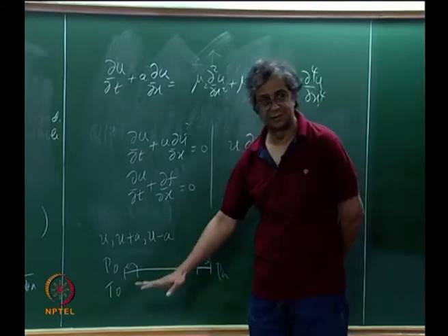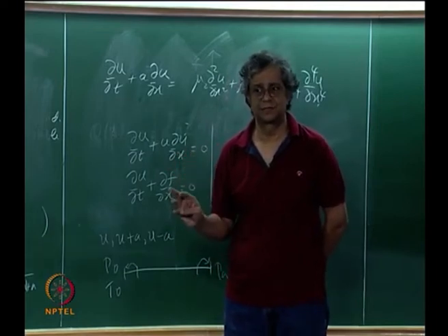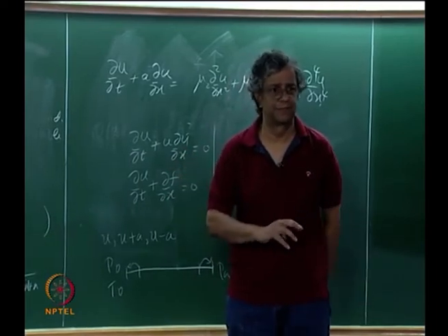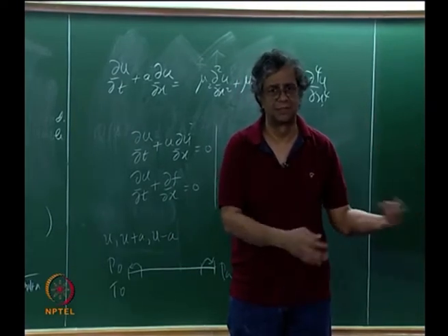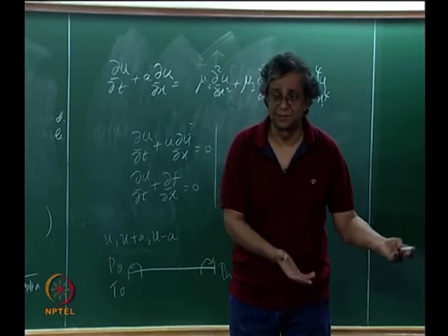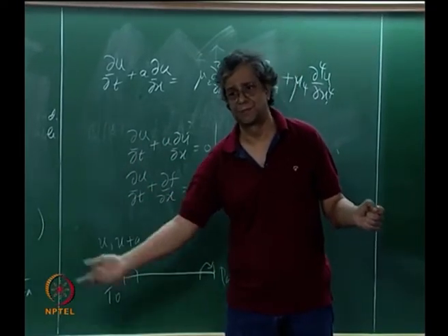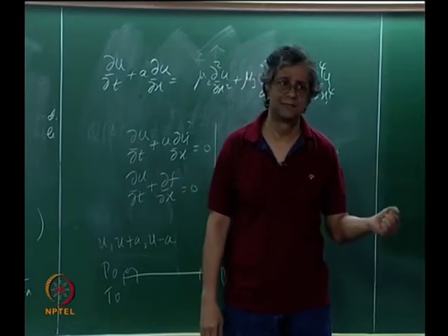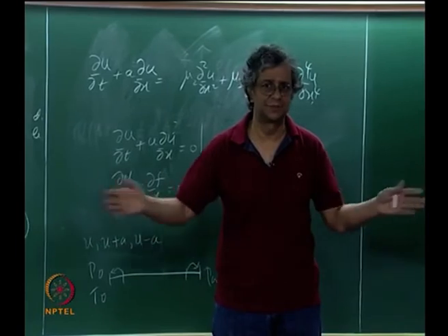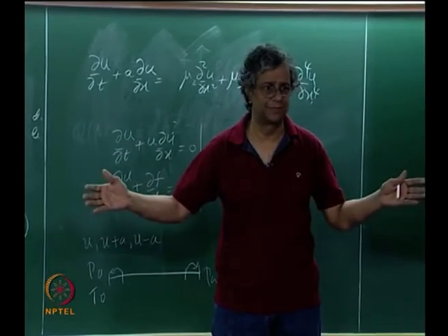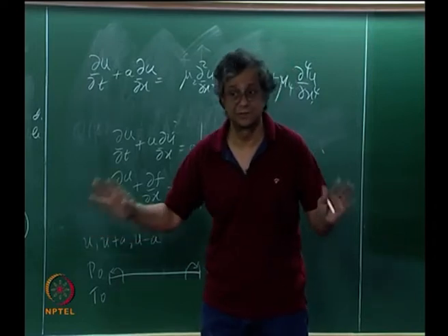The emphasis here is there are boundary conditions that you recollect, there are boundary conditions that are required by the physics of the problem. Your pressure vessel, the air in it has a certain P naught, it has a certain T naught, these are measurable quantities. You have a pipe, you have a valve, there is an ambient pressure, you open the valve, the ambient pressure and the P naught basically determine the speed with which the air is going to flow. Am I making sense? And the T naught will help you determine the other parameters. That is what the physics requires.